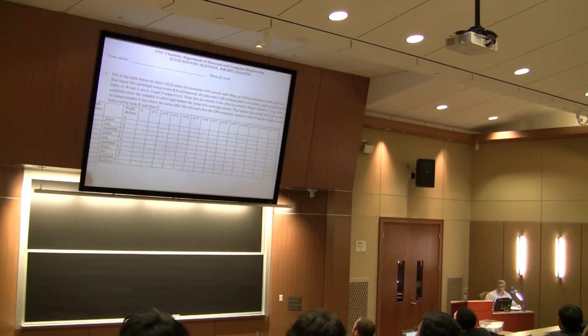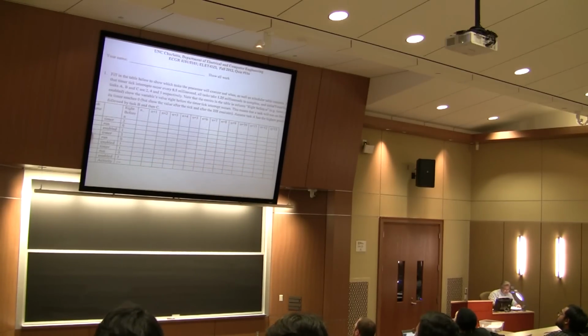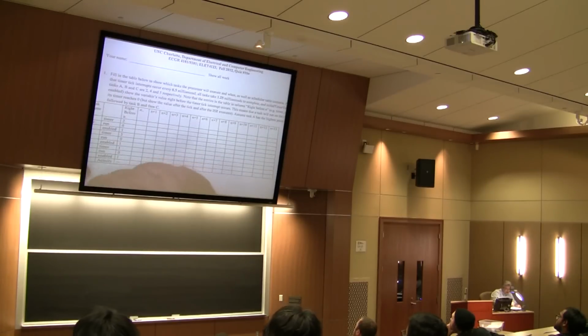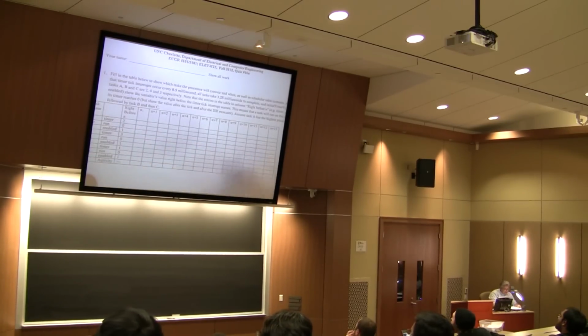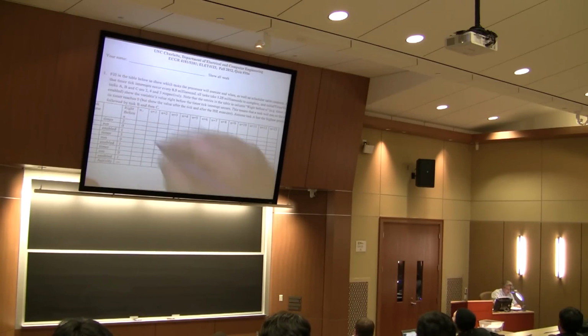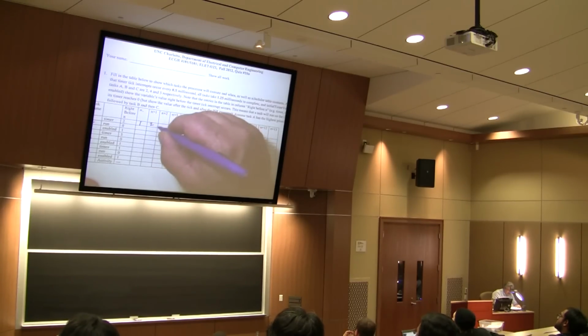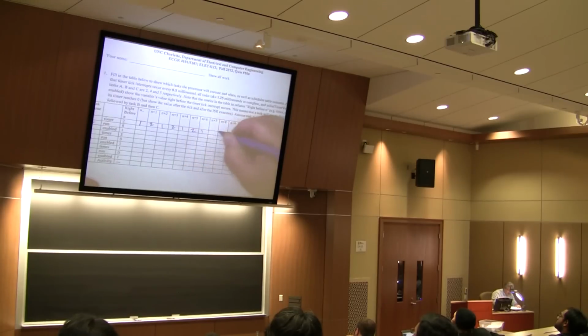One thing that we know about solving this problem is that A is called how many times? Every 2 timer ticks, right? B is called every how many timer ticks? 4. C is called how many timer ticks? 5. So that means I could look at these and immediately I could identify what all the values will be before I even look at what's going to run. So I know this is going to go from 2 to 1 to 0, which will then be reset to 2, to 1, to 2, to 1, and so on.